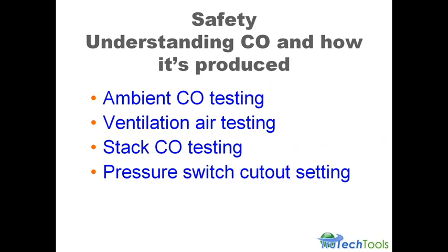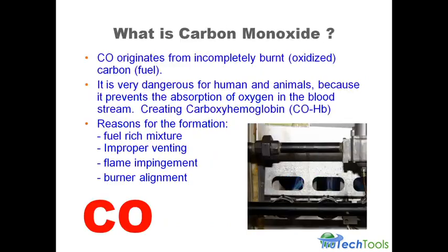We're going to talk about a couple things with CO: ambient CO testing, ventilation air testing, stack CO testing, and then I want to talk a little bit about pressure switch cutout settings on power burners and things that have adjustable pressure switches.